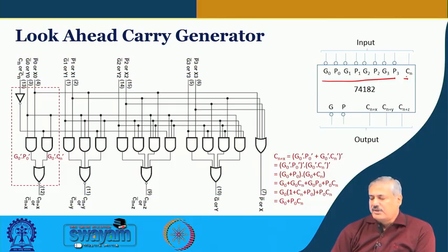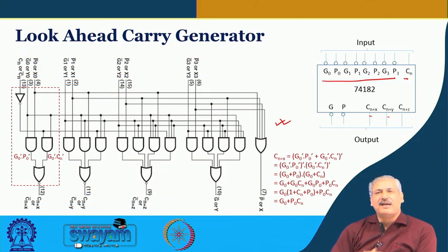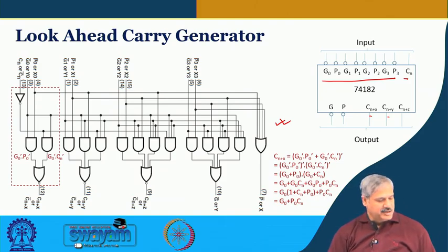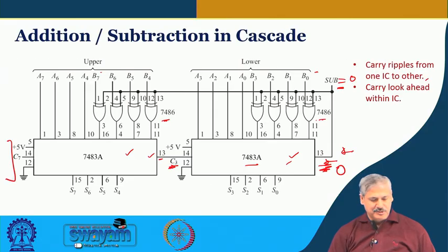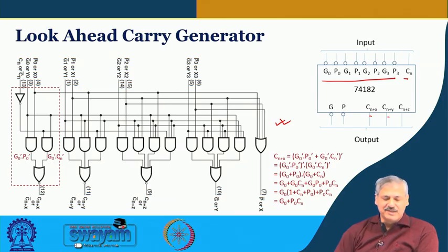And this is the input carry, and these are the output carries for individual stages, and this is the final group generation term and propagation term for multi-level use, next level use. Okay. And this is the corresponding circuit, and we said that again we have inverters, then NOR gates and other things, like the example that I had given before. So, let us investigate one such particular block and see whether it matches with the equation or not. Okay. So, this is the block that we look at.